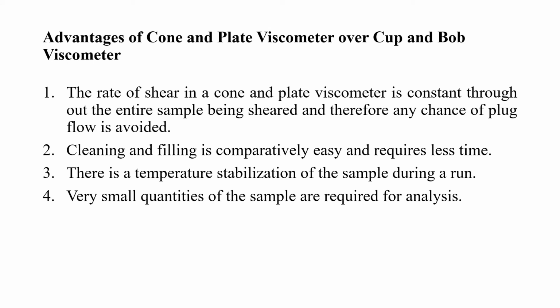Now let's see the advantages of cone and plate over cup and bob. The most important advantage is the quantity of the sample. We need only little amount of sample to be analyzed in cone and plate viscometer. And the cleaning and filling of this equipment is much easier.